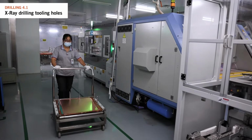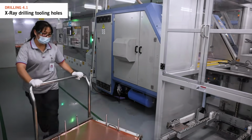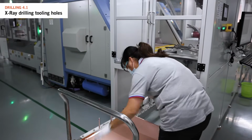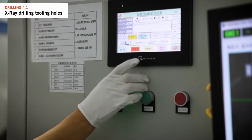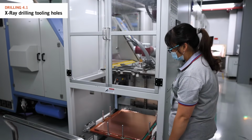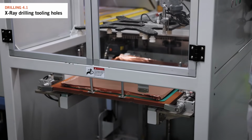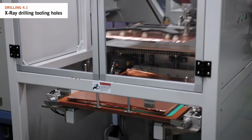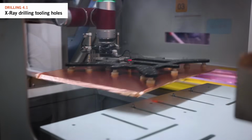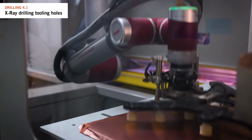After lamination, all internal reference markings that show where we want to image the outer layers and where we shall be drilling in relation to the position of the inner layer features are now hidden in the multilayer panel. Failure to align upon those internal reference points correctly could result in our drill location not making precise contact with the copper feature on the inner layers, risking potential weak connections.